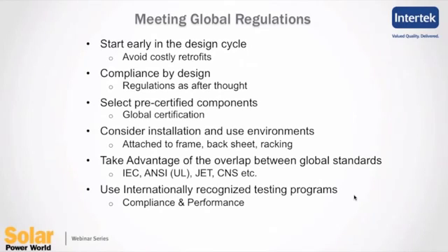One of the biggest non-compliances we noticed during the evaluation process, the certification process of any renewable energy products, is components. A lot of people use components that are custom built for a certain product, or components that might be a few cents cheaper because they don't carry a lot of the regulatory certifications. Instead, select components that have global certifications already completed before you put them together and build your optimizer or build your microinverter.